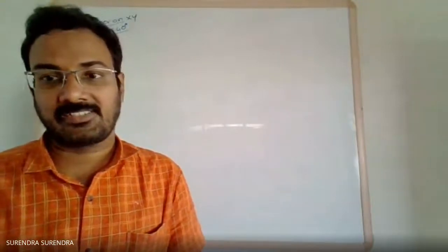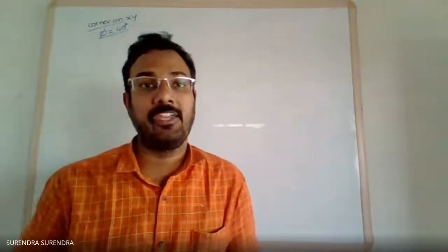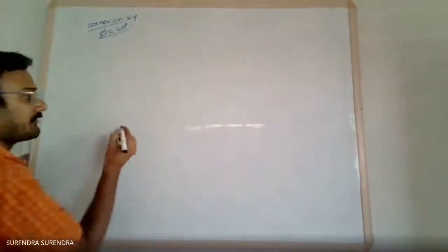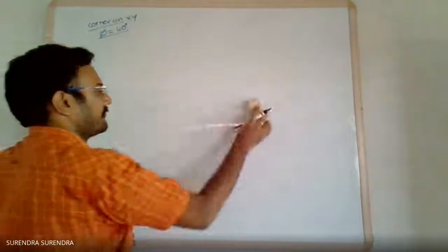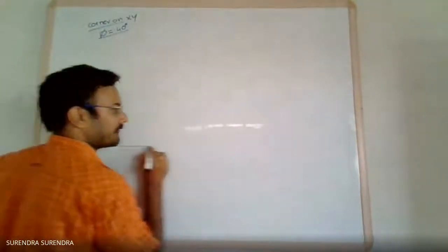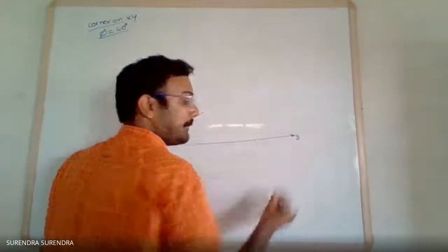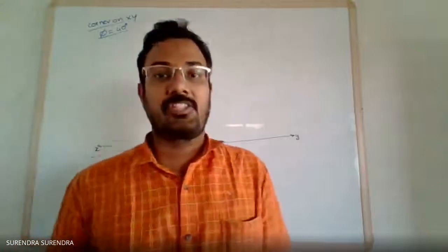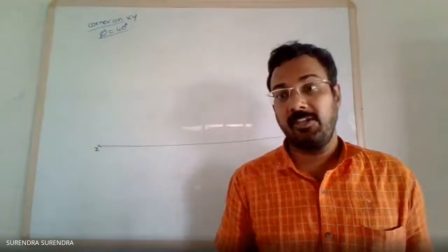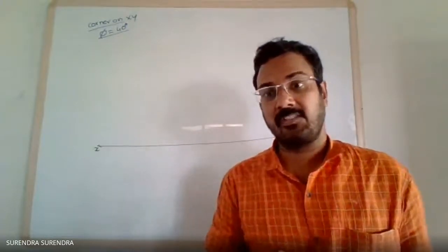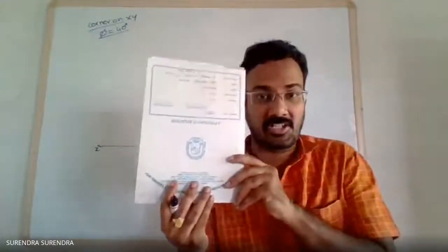The surface is inclined at 40 degrees to VP, as given in the problem. So as the surface is inclined to VP, the initial condition is to make the surface parallel to VP. So as the problem is inclined to VP, first let us make the surface parallel to VP. Second, perpendicular to HP, which is a condition? Yes, it is perpendicular to HP and parallel to VP. This is the initial condition.